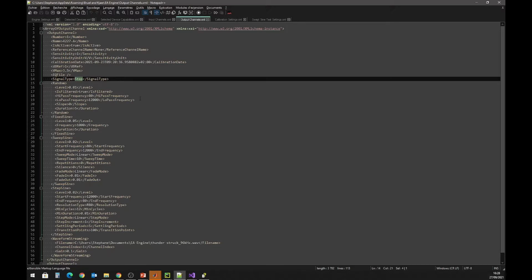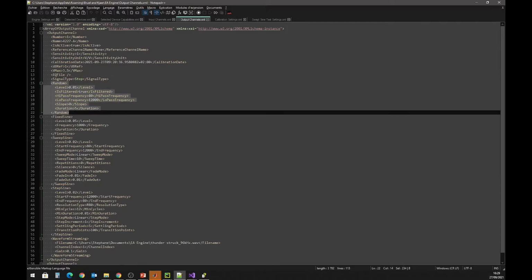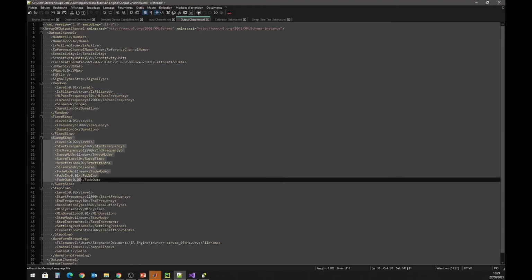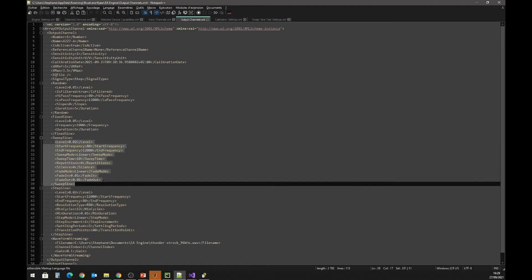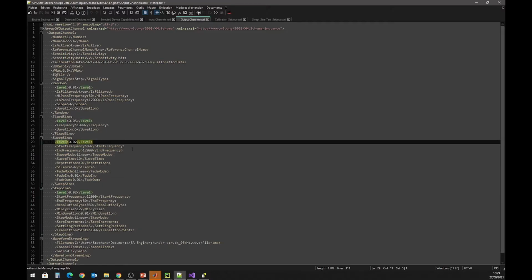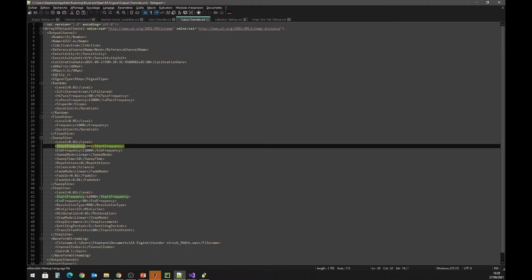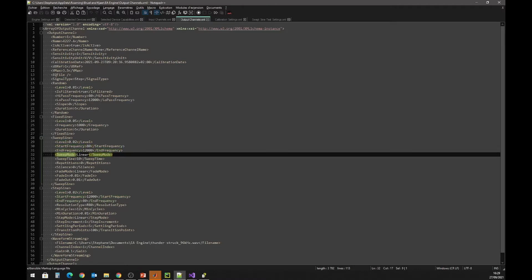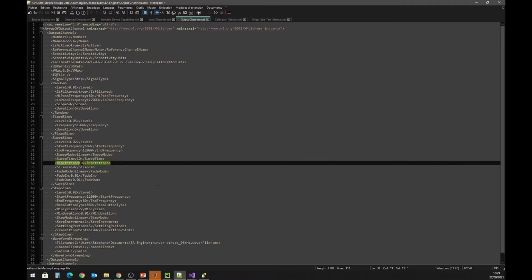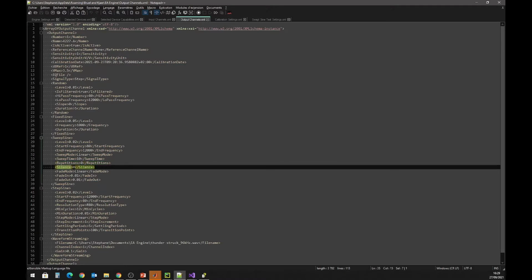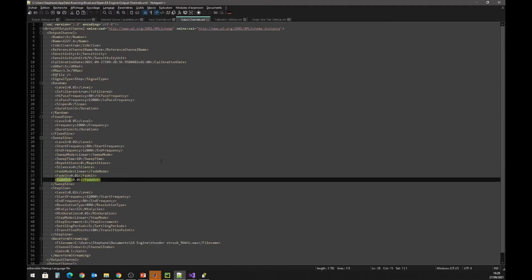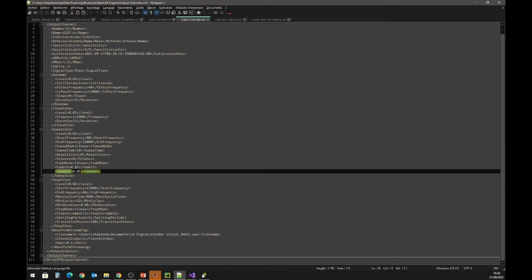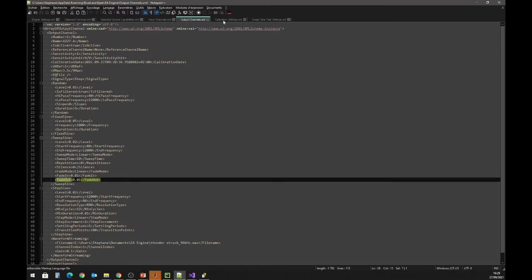And depending on this option, the software will know where to take the corresponding parameters, the corresponding settings. For example, for a sweep sine, it will go here to know the level of the sweep sine, the start frequency, the sweep mode, the sweep time. If we ask for repetition, if we want to insert silence between different sweeps, the fade mode, and fade in and fade out duration at the beginning and the end of the sweep. That's the same for the others, but with specific settings.